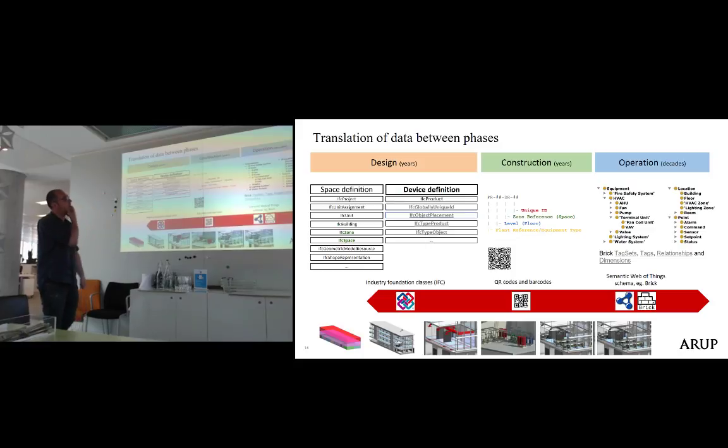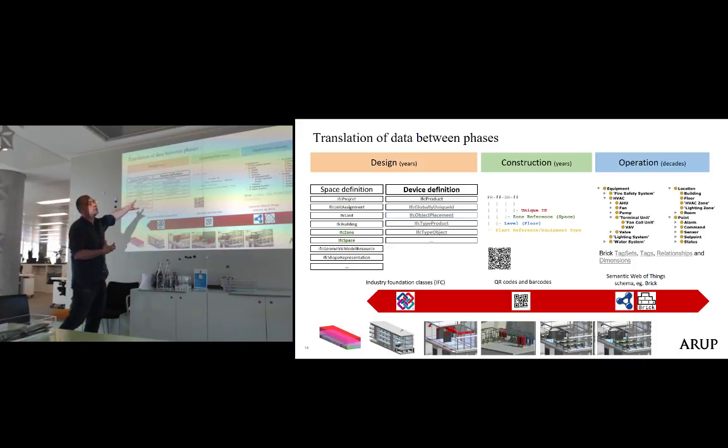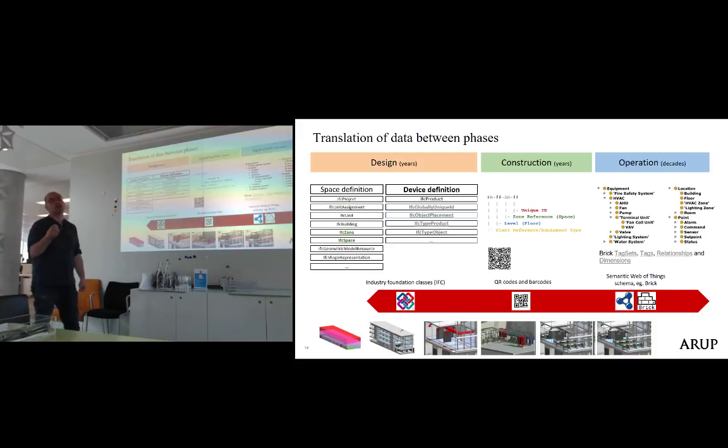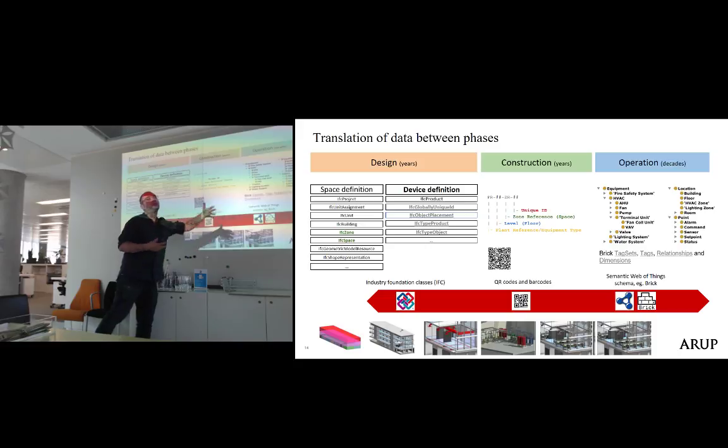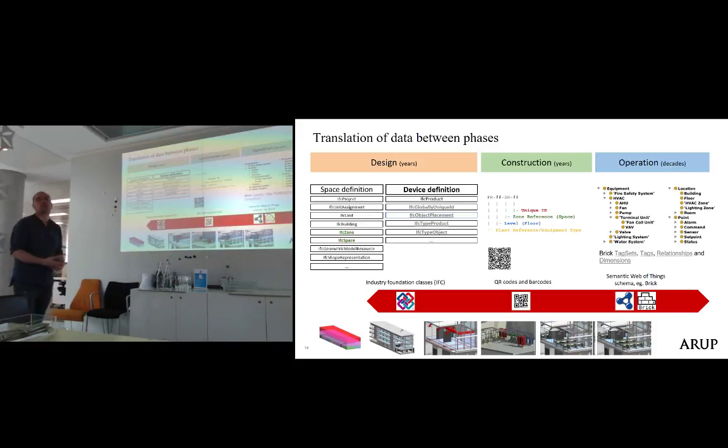There is a system called Brick. In BIM, no one would model an endpoint like an input-output of a device, while here we can model input-outputs of devices, so we can have a full description of the building, which can then be programmatic. Instead of doing spreadsheets, we can create a network of how things are connected, and then push it to the building. That's the sort of idea.